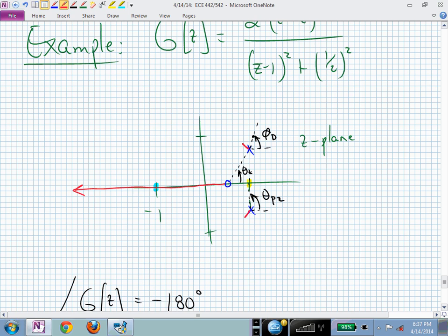Now, if I'm circling my breakaway segments and I'm boxing my reentry segments, do I have either of those in this diagram? I better have a reentry, hadn't I? Because these two branches start off the real line, and eventually they're going to have to end up on this real line.